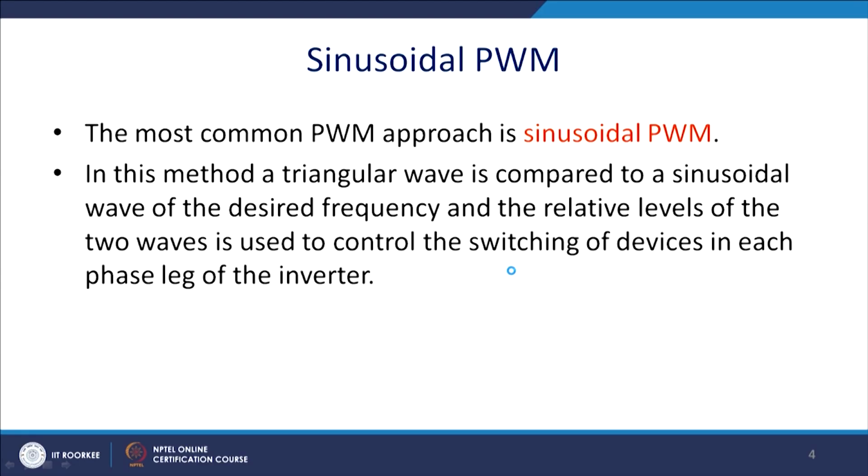Now, as told in the previous case, the most common approach is sinusoidal PWM. Here the sine wave, which is mostly the control wave or the modulating wave, is compared with the triangle wave, and accordingly the reference will be generated. We can see it in the next slide.